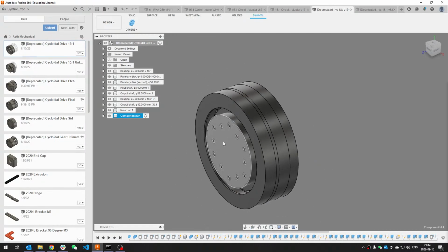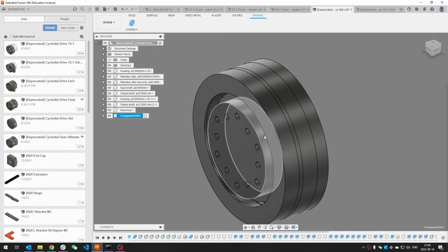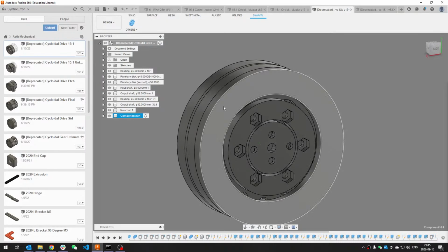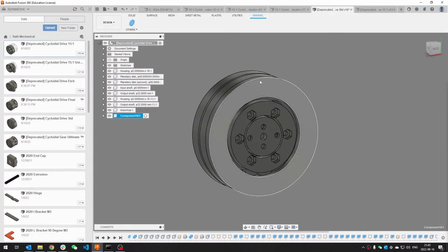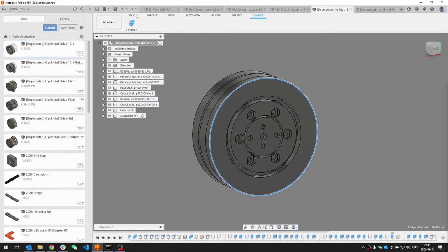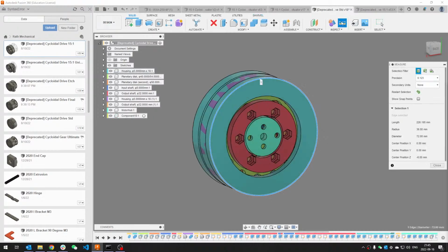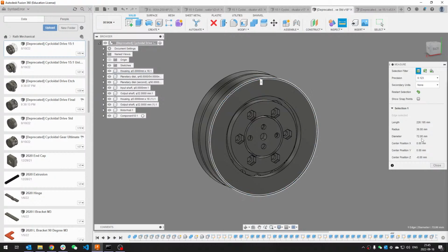In the basic form, for these small ones I was designing for the elbow joint. So it uses a small 5010 BLDC motor, and the diameter of the housing is then like 72 millimeter.